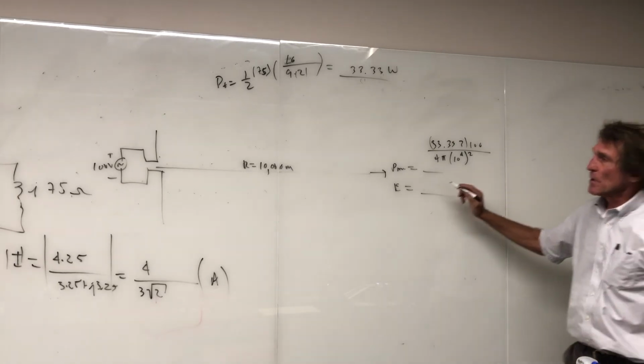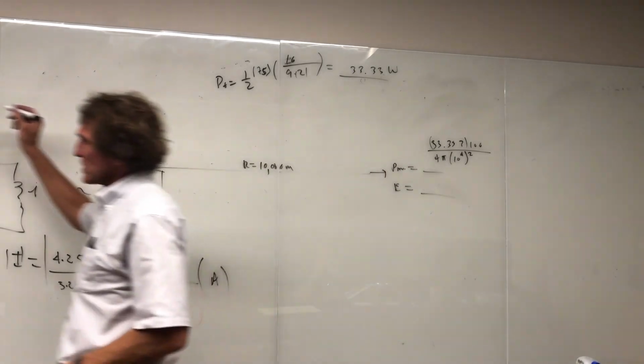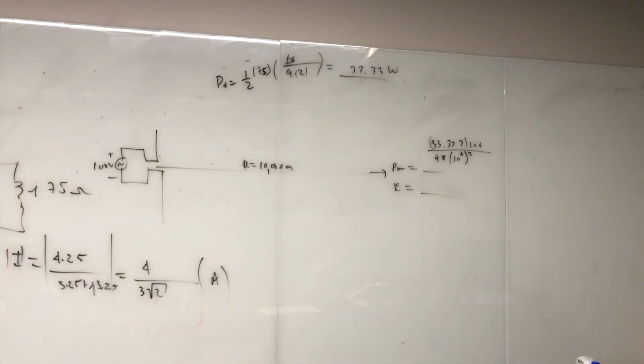Why is it 100? Well, the gain of 20 dB is really what? I put that up here somewhere, I guess I erased it. Gain in dB, if you don't know this, write this down. dB power is always going to be 10 times log. Gain is a power-related term. It's 10 times the log, base 10 log, of the linear gain.